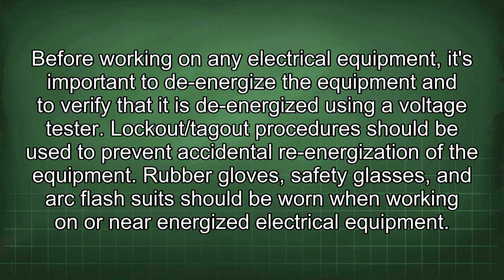Before working on any electrical equipment, it's important to de-energize the equipment and to verify that it is de-energized using a voltage tester. Lockout/tagout procedures should be used to prevent accidental re-energization of the equipment. Rubber gloves, safety glasses, and arc flash suit should be worn when working on or near energized electrical equipment.